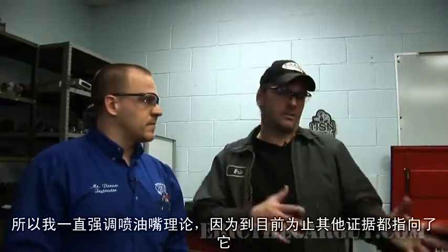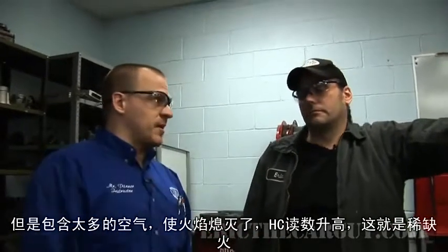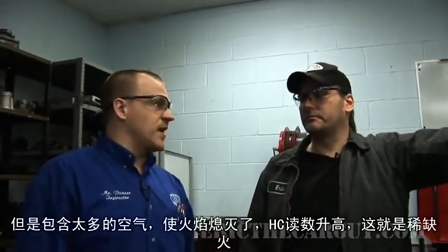So this is the reason why we continue to pursue this whole fuel injector theory. Yes, because so far the evidence points to that. That's right. And the other thing I didn't even think about: if it was an intake runner leak, we would have had high hydrocarbon readings. Maybe we would have seen something different on the gas. Absolutely, because you're still getting the fuel in that cylinder. You're just getting too much air, and it's putting the flame out, and our hydrocarbon levels would have been real high. Exactly. Lean misfires mean high hydrocarbon levels. So there is some method to this madness. Absolutely. All right, so let's take a look at the injector.